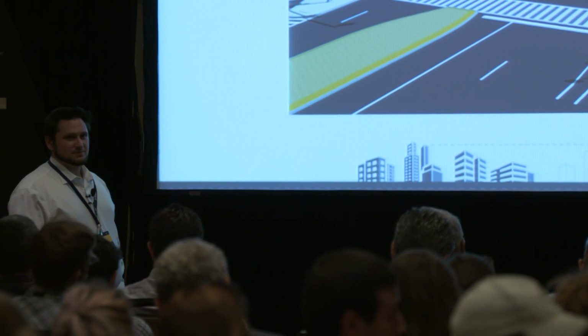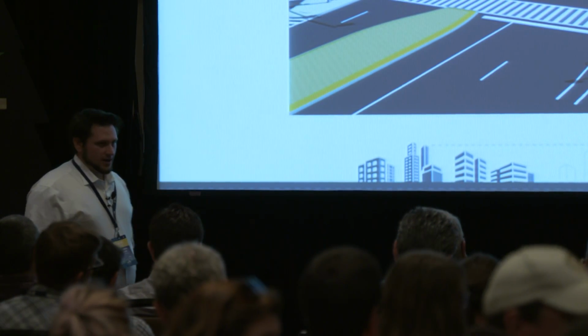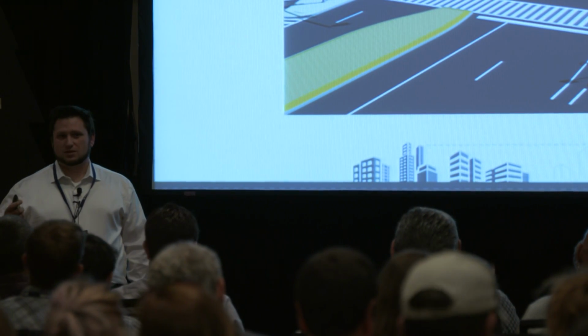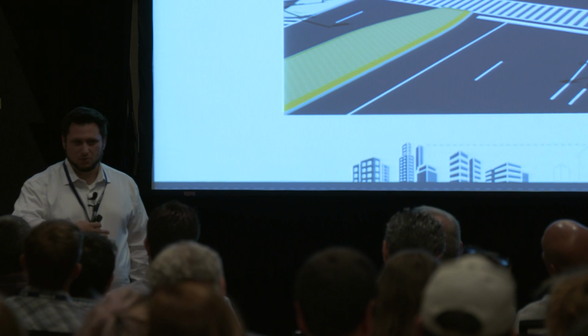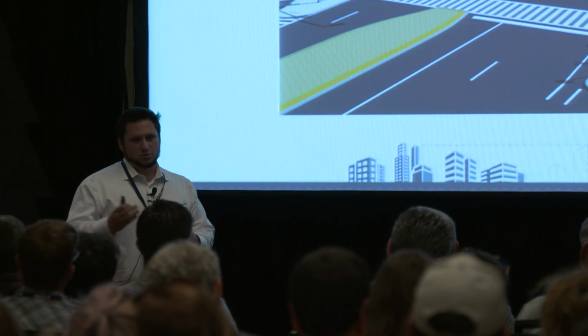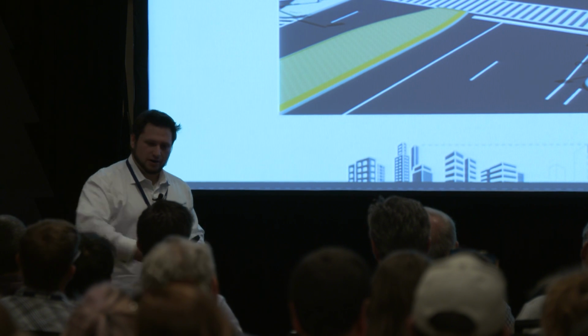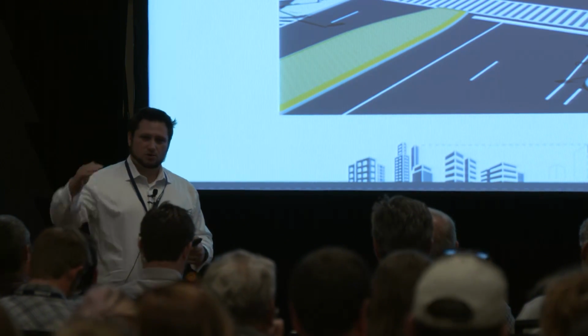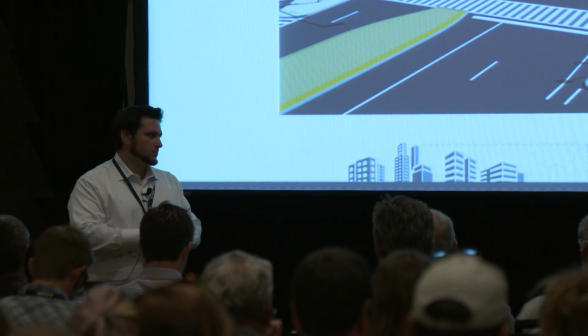There's also the AutoCAD polyline. Yeah, so one other workaround we use is for CAD users, if you've used the measure tool in CAD to basically do an array of blocks, we'll do that. The block comes into CAD, it's already on the whole curve, and then we can either move it down if it's flat, or if it's arched, we can drape it onto the arch.